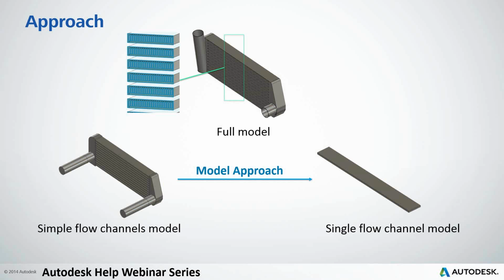So I got a fully developed flow at the inlet, and I extended the outlet to avoid any recirculation when measuring pressure drop or velocity there. The approach I adopted is to take only one large channel and delete these small tubes.